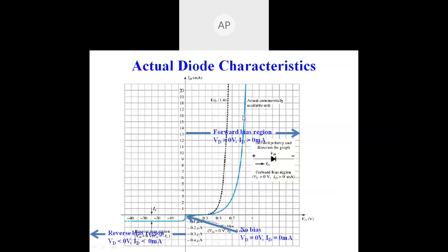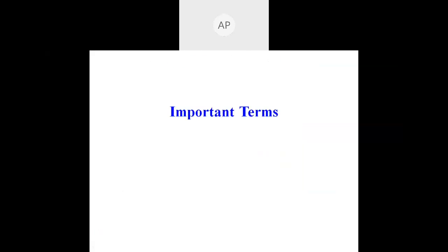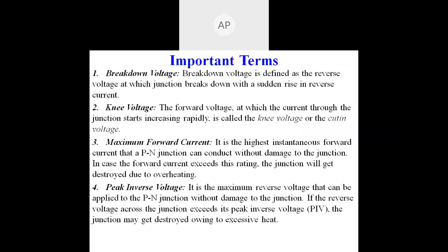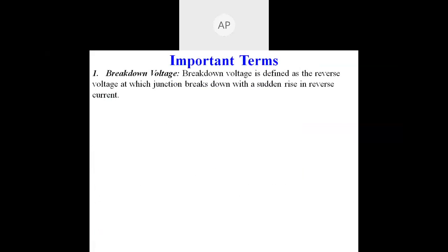Can we go beyond this? Yes, you can go beyond this, no issue about it. But if you go beyond this, a very large current will flow through the diode, and this will damage the diode. So we have to limit this maximum current. For that purpose, we need to connect an external resistor to limit the current flowing through the diode circuit.